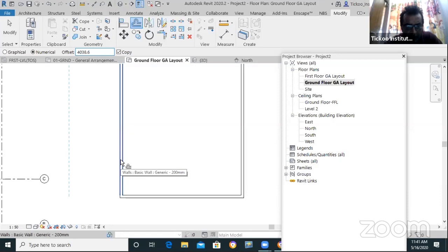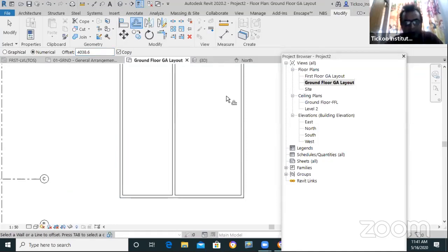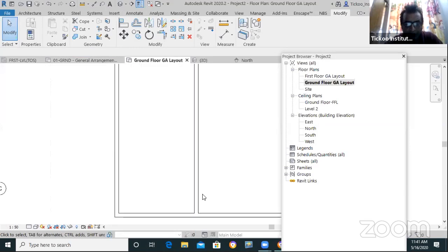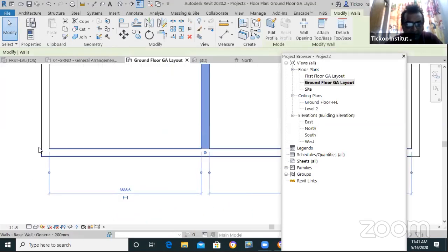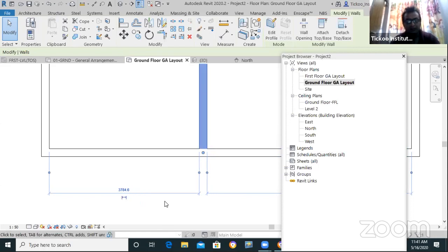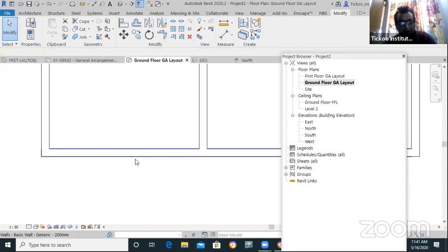Now, if you click on this part, the dotted lines will be on the left. It's showing that the offset copy will be created there. But just move the mouse, because you need to place the offset on the right hand side. So click on it. Now if you measure it, you will find that a particular distance has been set from center to center. Now if from the clear space you want to have, let's say, 12 feet 5 inches, the clear dimension can be that.